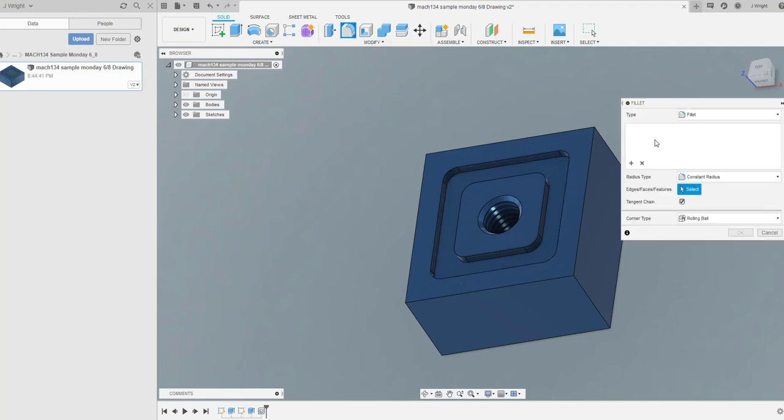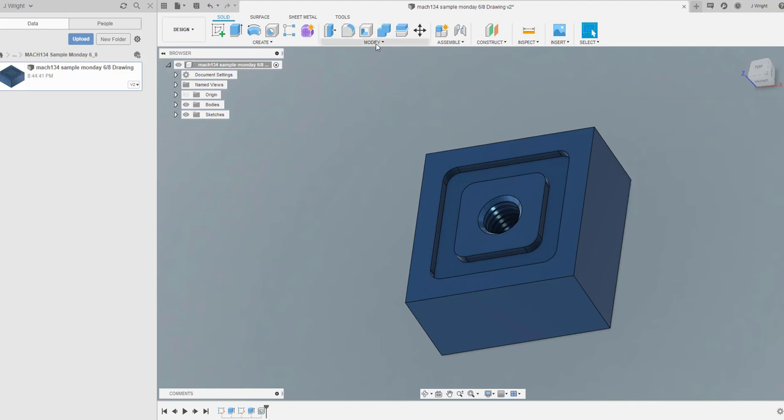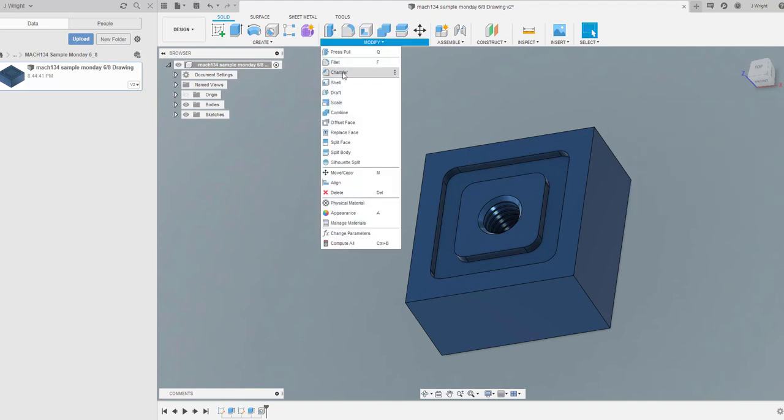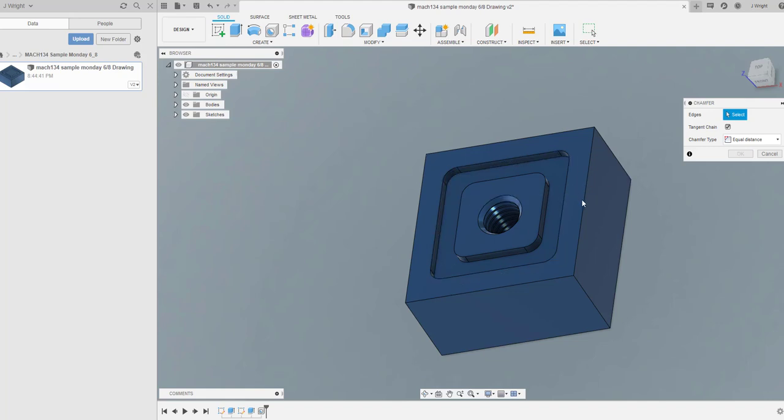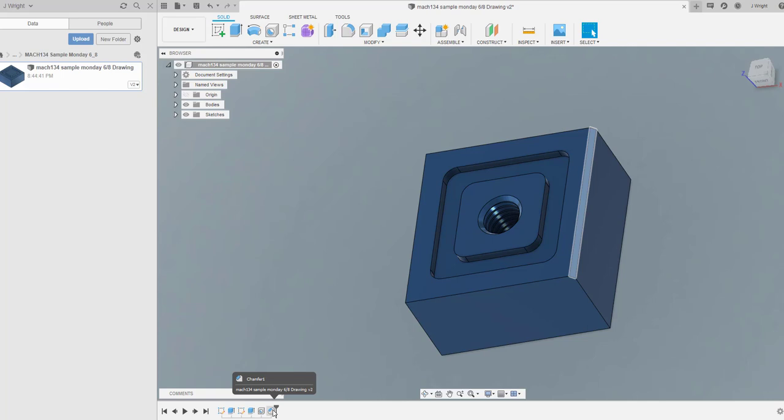So while we're here, another command that I use a lot in this area would be this radius chamfer section, where I can create fillets or radiuses around my parts. Typically I'll come down here and start it from here. I maybe do a chamfer around my part. I might click on this edge and then just hit 50 thousandths, and then I've got that edge. Now my timeline is showing it. Now if I decide I don't want it in there, it's gone.